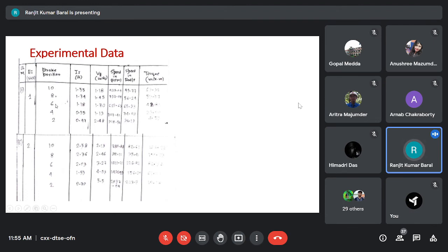Now, when we decrease the brake position, the load torque is getting reduced. So the speed will go up. See, from the reading of the tacho generator, we can estimate that the speed has increased. Now you can calculate approximately the motor torque and the shaft speed from the previous table.